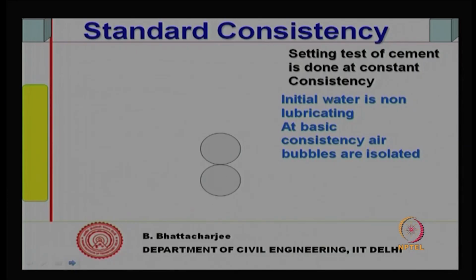Now, that consistency corresponds to basic water content as I mentioned, and consider this is a cement particle, another cement particle and another one and another one. For simplicity, I am assuming they have simple cubic packing, and the space here is air void.